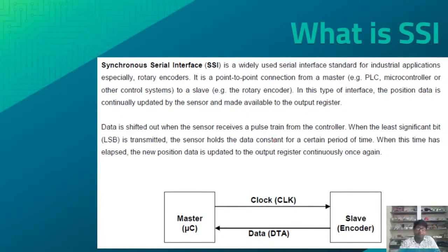In the case of parallel communication, say I want to transmit 13-bit data, I need 13 wires, 13 connections. And moreover, if any particular one bit is not transmitting properly or there is some error, the measurement will have a huge error. But if it is serial communication, then it will be going as a packet, so all those possibilities will be reduced.